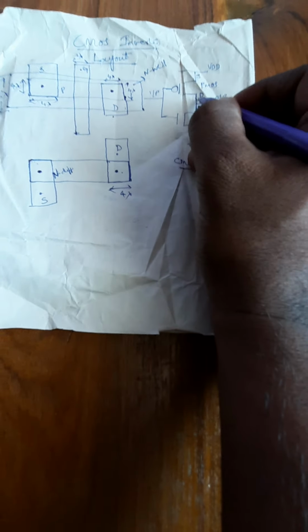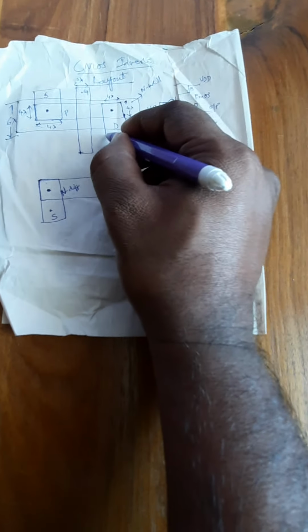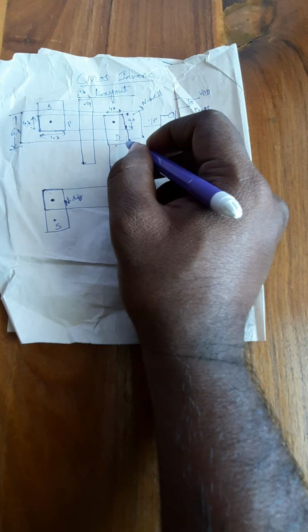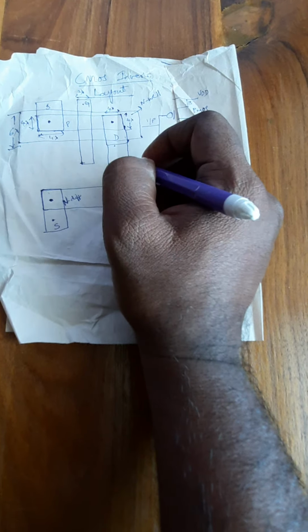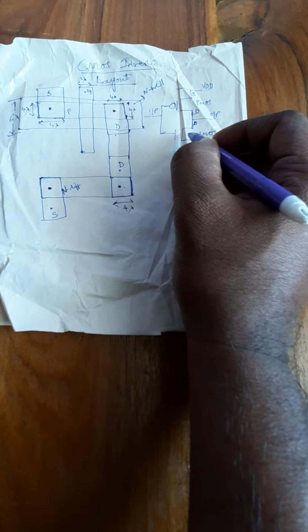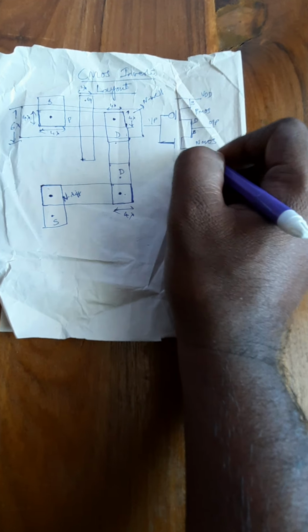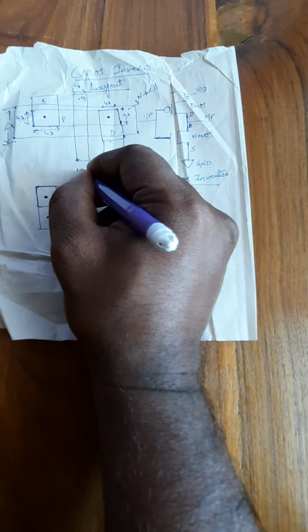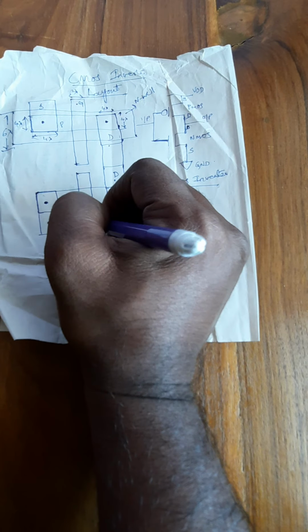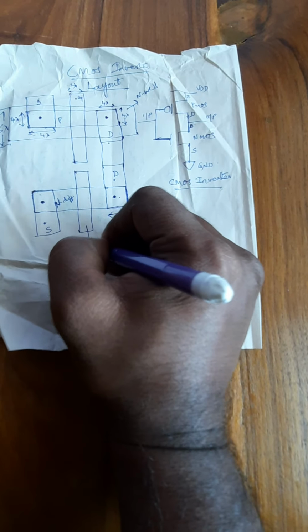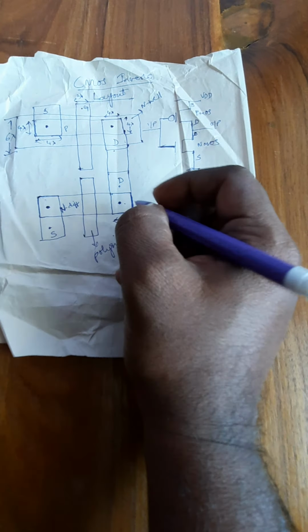And you can see now here both the drains are connected, so short both the drains. Since both this drain and drain are of the same kind of material, there is no need of using any kind of contact over here. And after completing the source and drain of NMOS, now you can draw the gate terminal. The gate terminal of NMOS will be drawn with the same kind of material which is used to draw the gate of PMOS, that is polysilicon. We are drawing it with polysilicon and the width is 2 lambda.